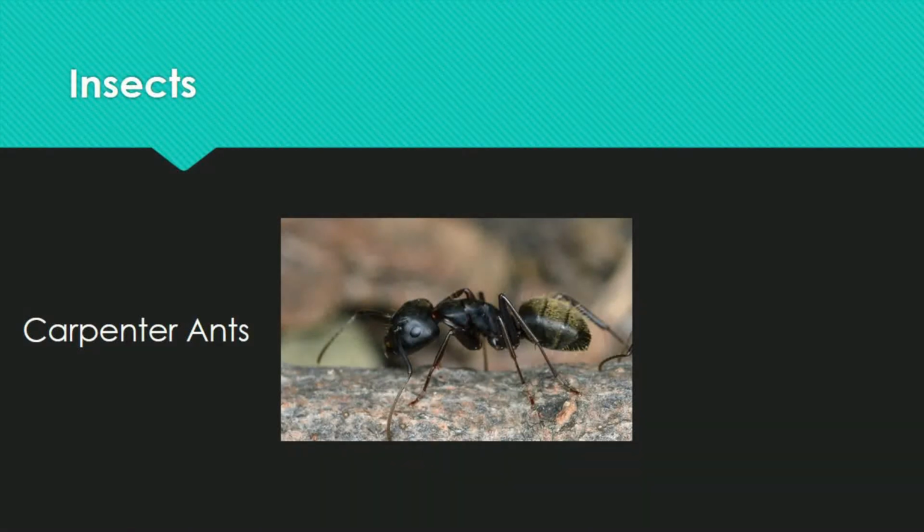Aside from fungi, there are several types of insects that affect the integrity of wood. So let us start with carpenter ants. The most common insects seen during pole inspection procedures are carpenter ants. They reside in colonies and make nests in poles for shelter, but they don't actually eat the wood. An amount of sawdust at the foot of the pole would usually indicate the presence of these carpenter ants, and these ants may often be observed swarming around poles looking for food.